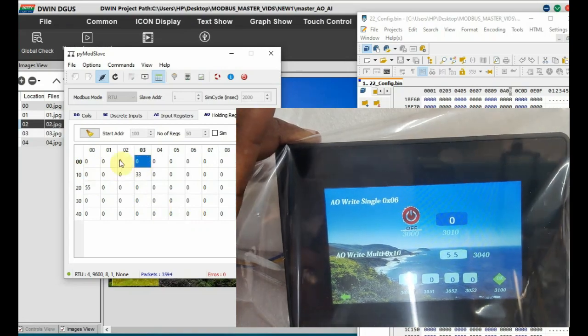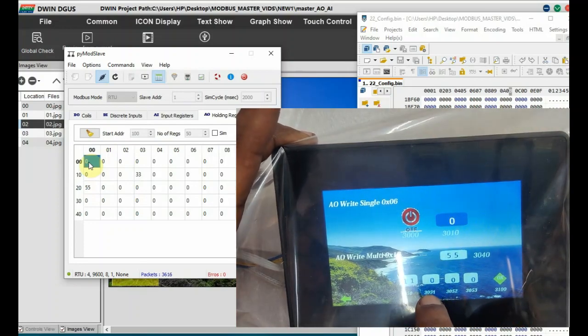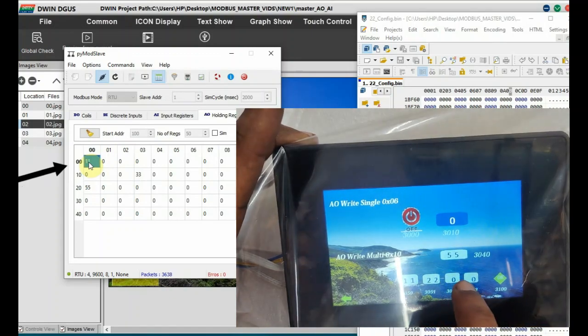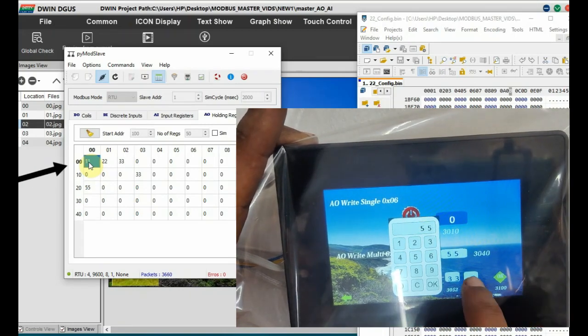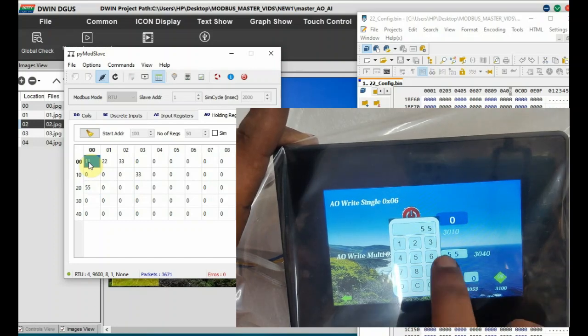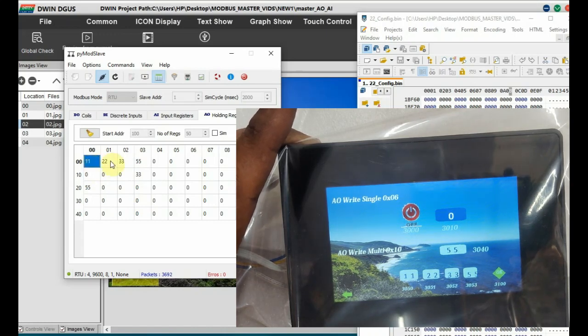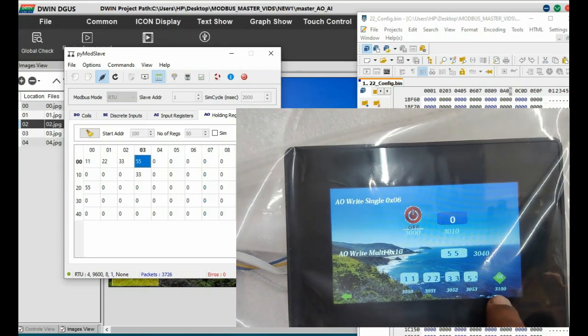And for multi, feed in from 3050. The keyboard will pop up. This is from master to slave. So we are feeding using the keyboard. At first, at location 100, which is 0064, the data will vary. The next VP addresses are 3051, 3052 as well as 3053. All these 4 VP address data will be transferred to the slave starting from location 100, which is 0064 in hex. So this is the 0x10 command, the write command. We are using it for single as well as multi-register update.